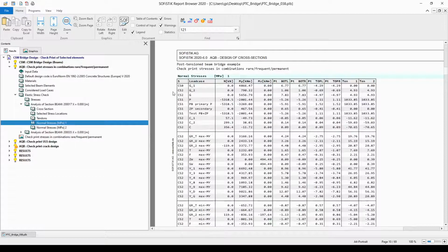This part of the table contains the G, P, and C effects of the combination rules. These internal forces and the stresses in the stress points will be used to combine, or superimpose, with the effects arising from the actions that are acting on the final cross-section.